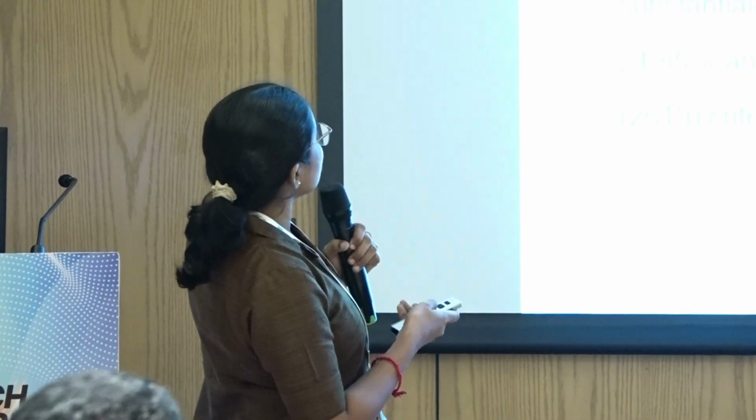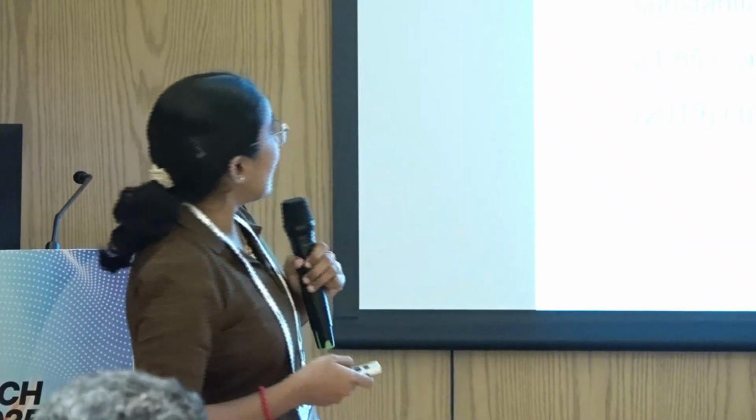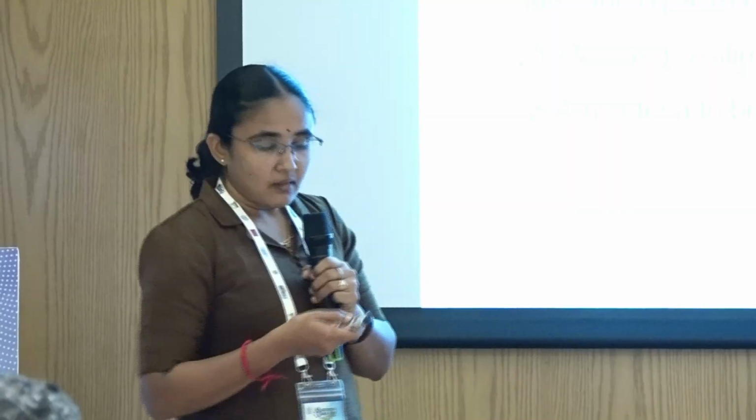So we conclude that uncrushed micaceous sand has a resilient nature. If we restrict the crushing, it itself behaves better, but that cannot be possible, because of abrasion the crushing happens continuously. But when we mix it with xanthan gum, and if we ensure that it is not undergoing that vulnerable saturated condition, xanthan gum is still a better solution. And if we expect extreme conditions of wetting and drying, bentonite provides the best alternative solution, which not only provides improved strength, but also helps in diminishing the crushing characteristics of mica.